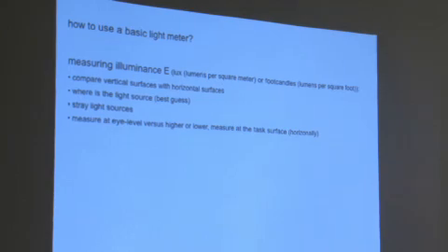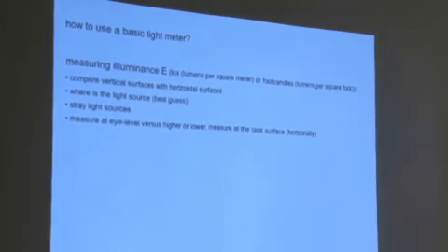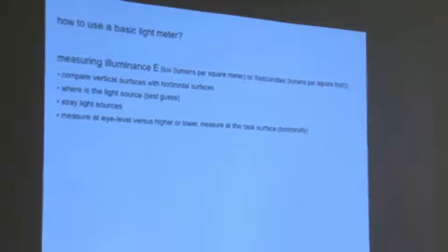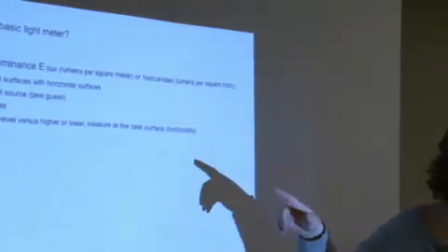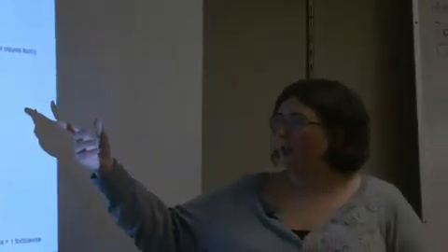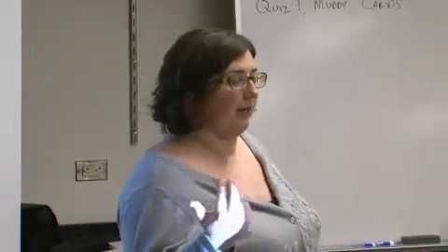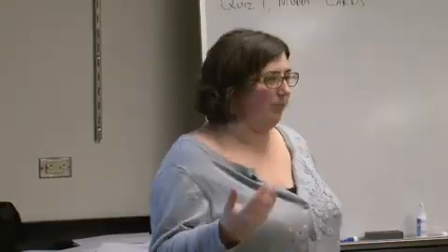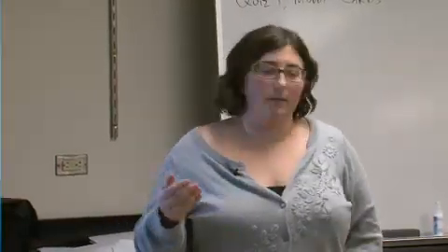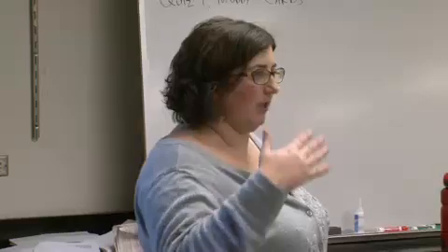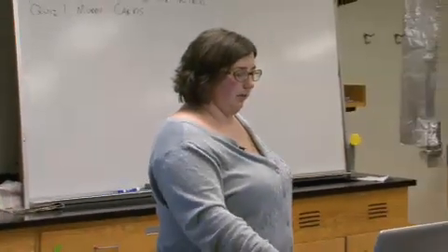There's my computer, there's the projector, there's the overhead lights. There would be light coming in from the windows of the doors if I hadn't covered them up. So you have to consider all of those, and then the straight light sources. And then whether you're measuring at eye level, and where exactly is eye level, are you assuming an average woman or an average man or something else? And then also at the task surface as opposed to the eye surface. All of those are important.